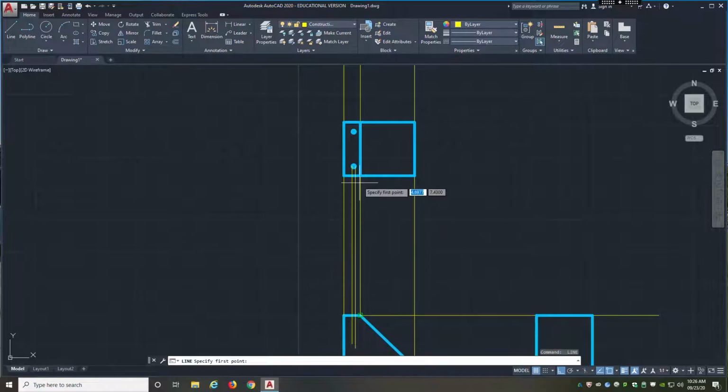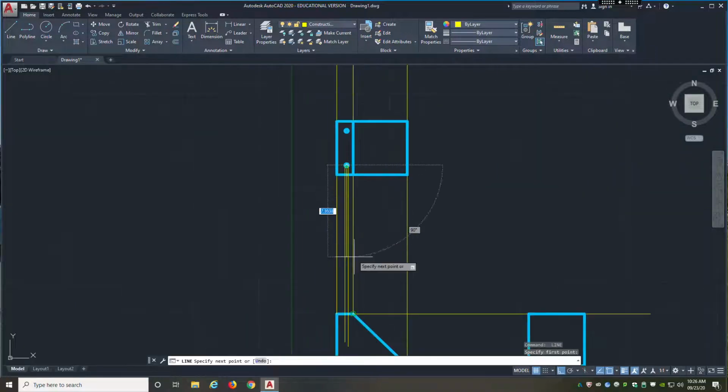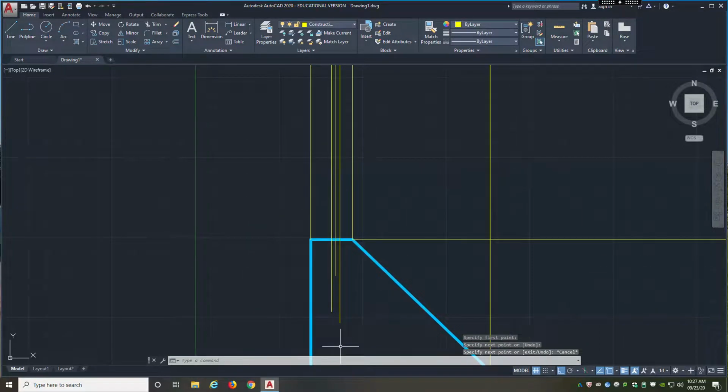Quadrant, that was this next quadrant. And finally get the center, make sure that we have the center all lined up. And as you're doing this, you might have to stagger those lines so that you're not seeing the same O-snaps pop up. Your line might jump to the next line. So stagger them a little bit just to make sure that you don't see O-snaps.